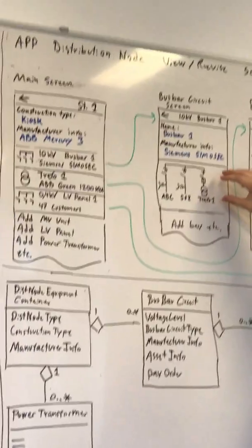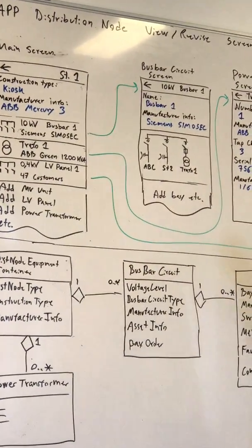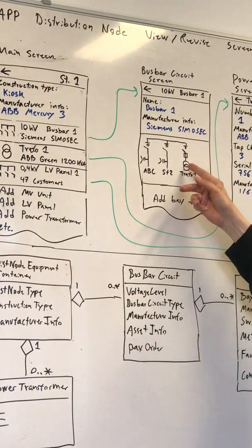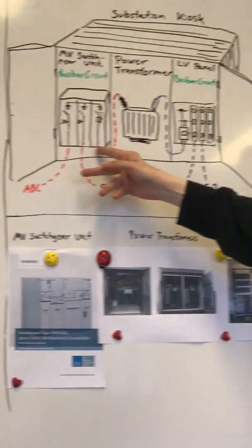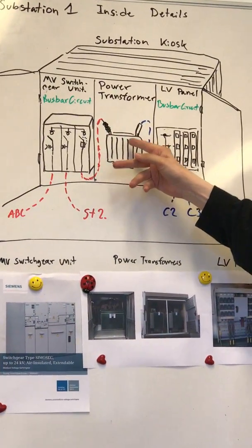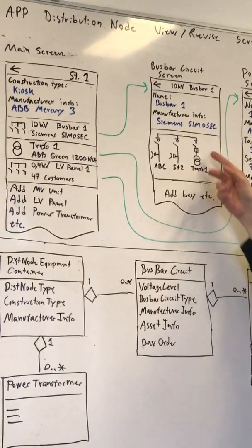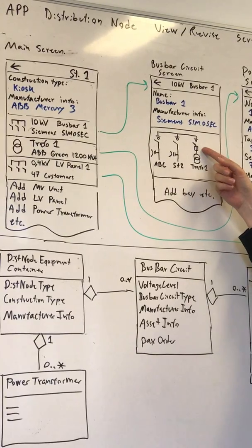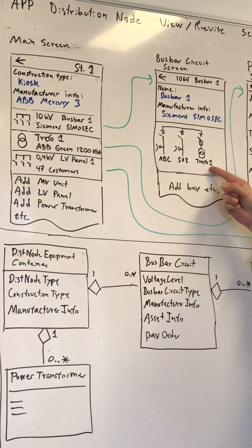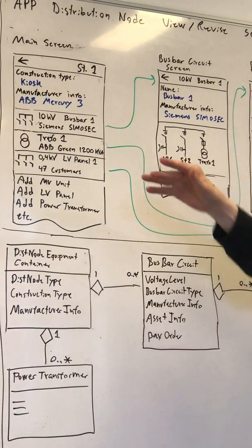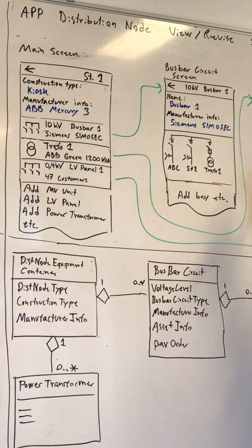You can see the single line diagram of the bus bar circuit. The difference is that we can see which one is connected to a transformer. So you can see here bay 3 is connected to the transformer. In this case it's transformer 1. This bay has a switch fuse that is typically used to protect the transformer, and then you can see it's connected to that transformer. If they had multiple transformers, you could see whether it's transformer 1 or 2 it's connected to. Right?